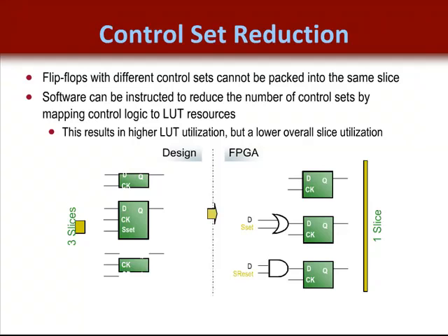or the Xilinx implementation tools can remap the logic to a LUT input rather than a flip-flop control port. When this happens, it allows the implementation tools to group the flip-flops into the same slice. And this is, of course, a good thing. Now, by the way, the reduced control set property for XST synthesis controls this result. But if you don't design with a synchronous set or reset, it won't work. So the message here is try to design synchronously with a synchronous set or reset.